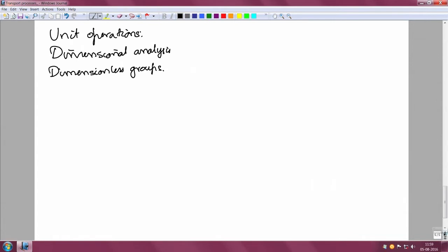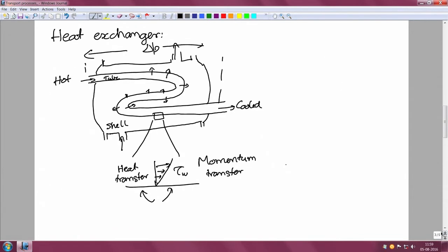So, if I wanted to design a heat exchanger, okay, the length of the tube and the size of the shell will of course depend upon how much temperature difference is there between the shell side and the tube side, how much the temperature of the hot fluid has to be cooled, in addition to material properties. It depends upon the specific heat of the material, the conductivity of the material, okay, and therefore, you have a relatively large number of parameters on which it depends.